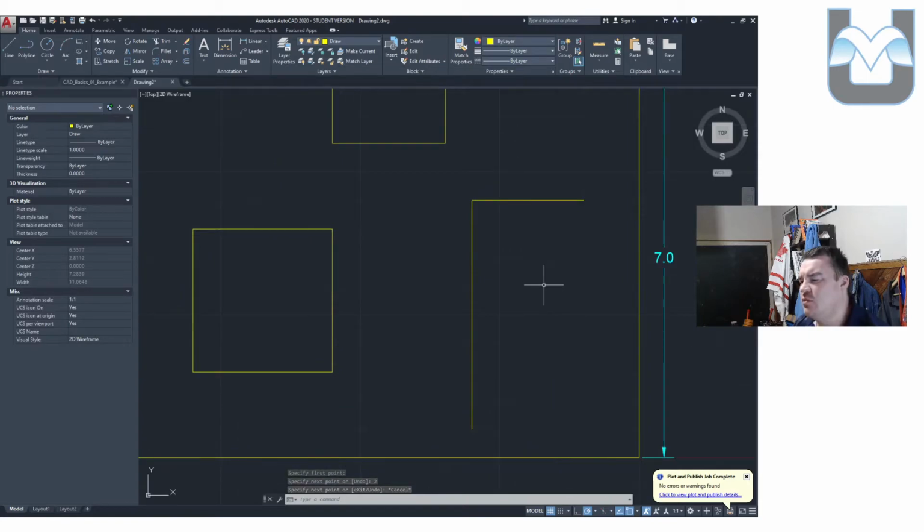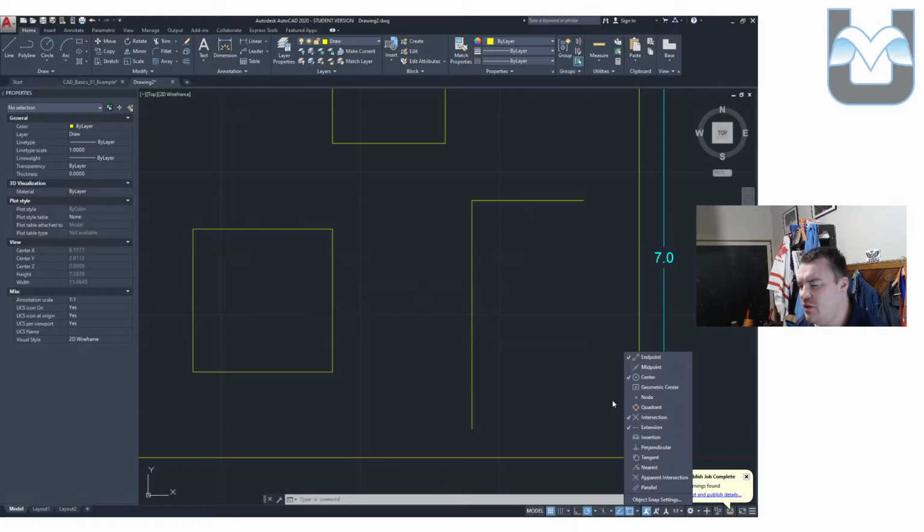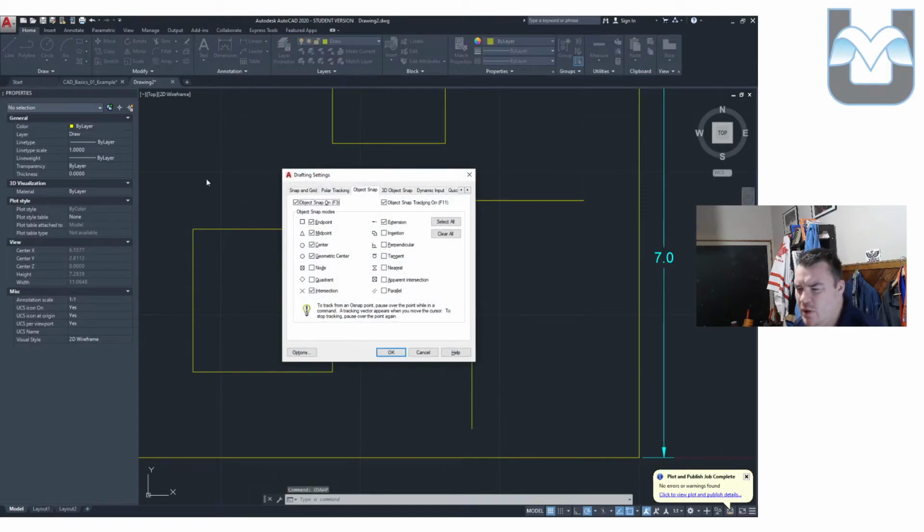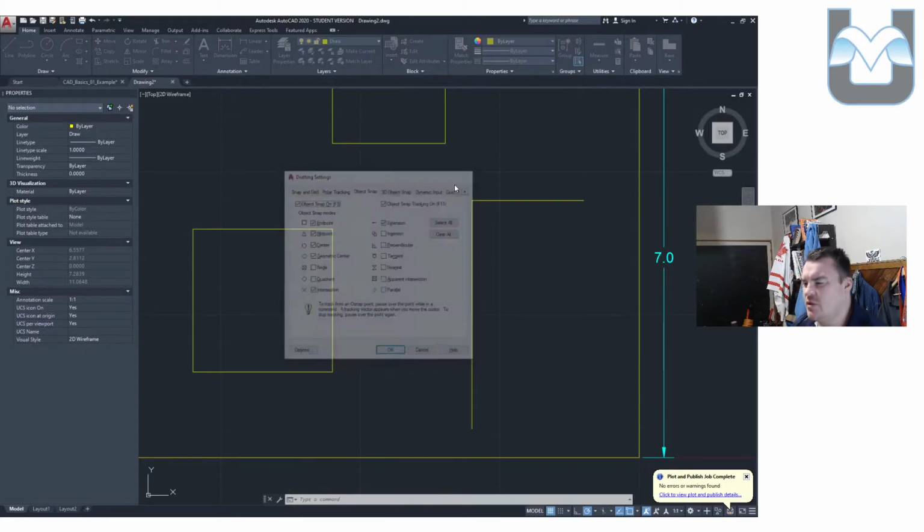That leads us to our very first tool that we're going to use here, and it's called the midpoint snap. If everyone floats down to their little menu down at the bottom here, you'll notice that you don't have midpoint or geometric center checked off. You have lots of options for things that can snap here, perpendiculars, and you can add different pieces of different shapes. I like to leave the defaults plus geometric center and midpoint. For the basics assignments, those are usually the best. If you also want to access this, you can type in OSnap, object snap, into your keyboard, and you get something that looks vaguely like this, and again, you can check off those things on the menu.